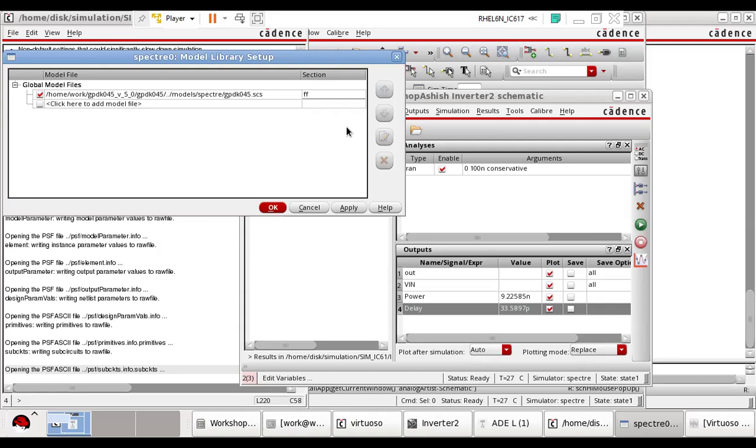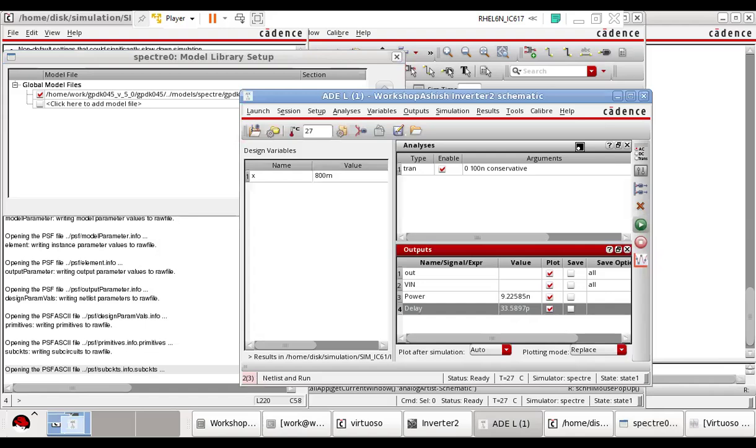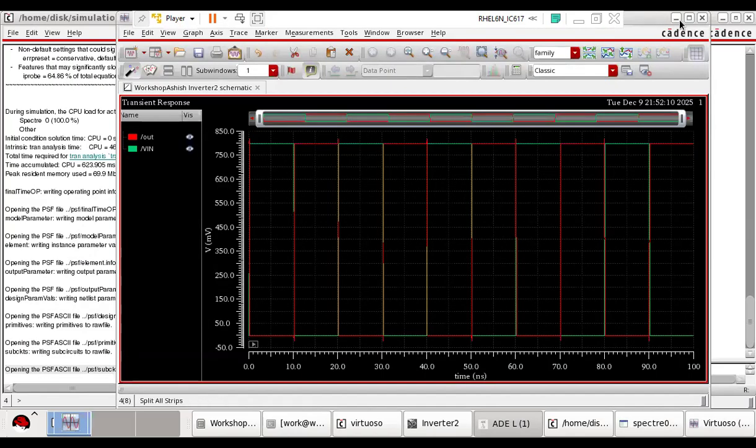Somehow, if your NMOS gets some corruption due to this external noise environment or any other environmental condition, what will happen to your simulation? What will happen to your results? Suppose this environment has impacted both PMOS and NMOS. In that case, we are assuming that both NMOS and PMOS have gone faster due to this impact. If I do simulation, then this will be the change in the power and delay.